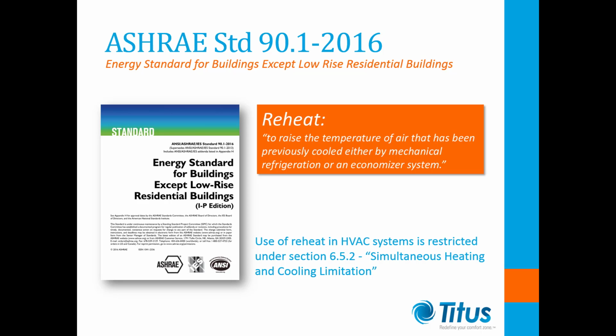But before we start, let's look at ASHRAE Standard 90.1. ASHRAE Standard 90.1 provides guidelines for the design of energy-efficient buildings and generally restricts reheat, which is defined as to raise the temperature of air that has been previously cooled either by mechanical refrigeration or an economizer system.